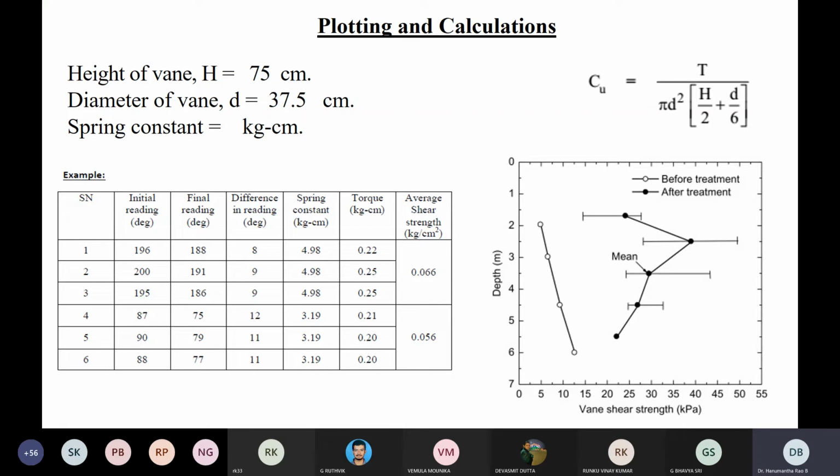And what happens when you put your leg on a clay soil sample? It slips. The slipping means the slippage of the water, not the clay part. Okay. Now, the more the water, the more the separation between the clay particles, and the least is the strength. Okay, I'm not talking about the compaction or something, but this is simple.